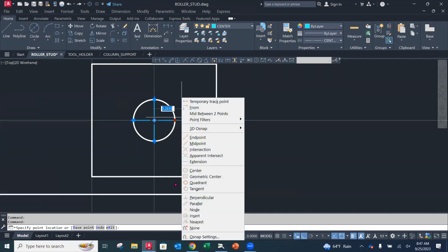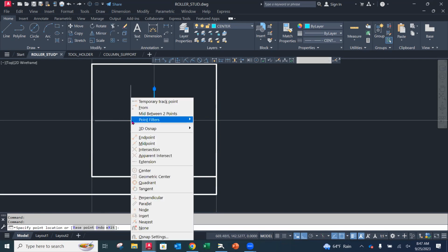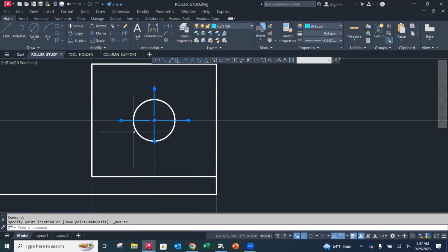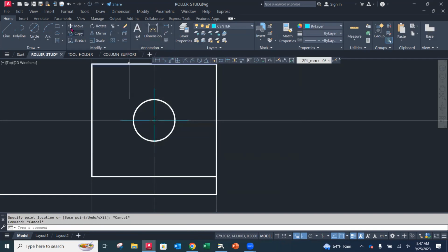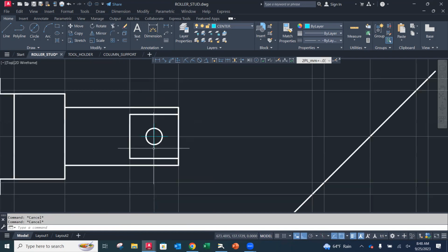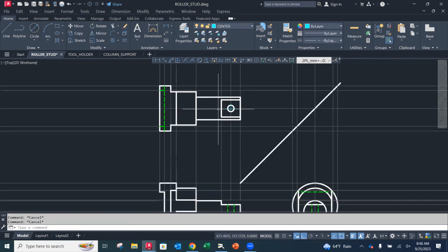That's all with the grips, and then just go nearest if you have a construction line down below that, and then nearest here as well. I don't know exactly where that is housed. Does that make sense? I know that one's kind of eh, and sometimes I end up just using regular center lines then. It's up to you. But you do have to correct that on these drawings. You can't just say, well, that's what AutoCAD did. AutoCAD's a machine. You're the human.